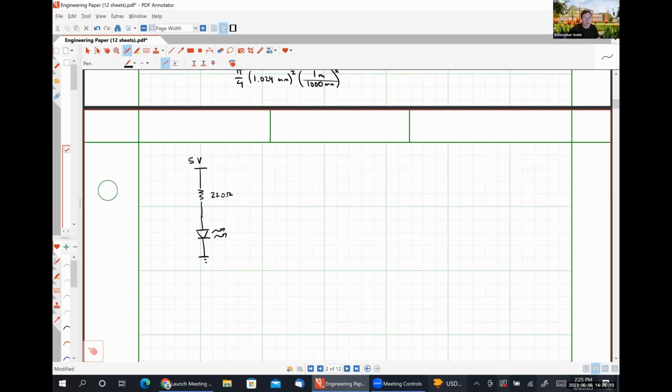Then the LED would get too much current and burn out. Exactly right. It'll shine really brightly for about half a second, and then it will never shine again because you've literally passed so much current that it is burned out. 100% correct. So the principal role of resistors is really twofold. It's two ways of looking at the same thing, okay? A resistor is used to limit current, and it does this by converting electrical energy into heat, okay?